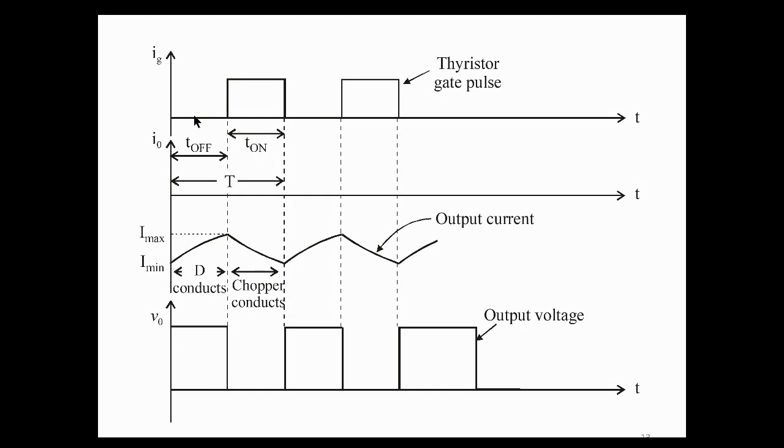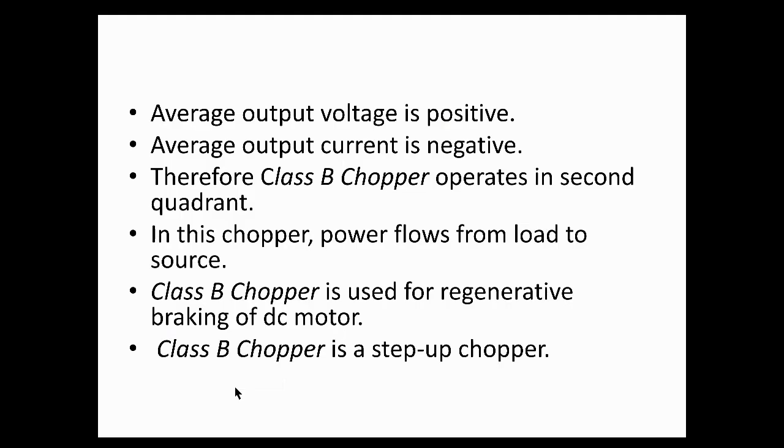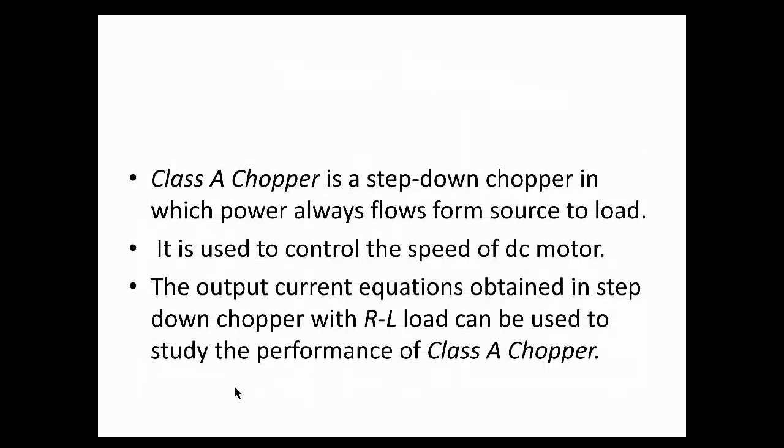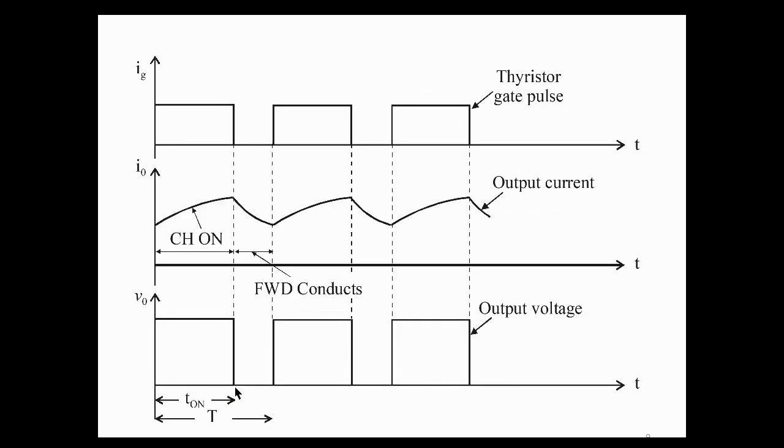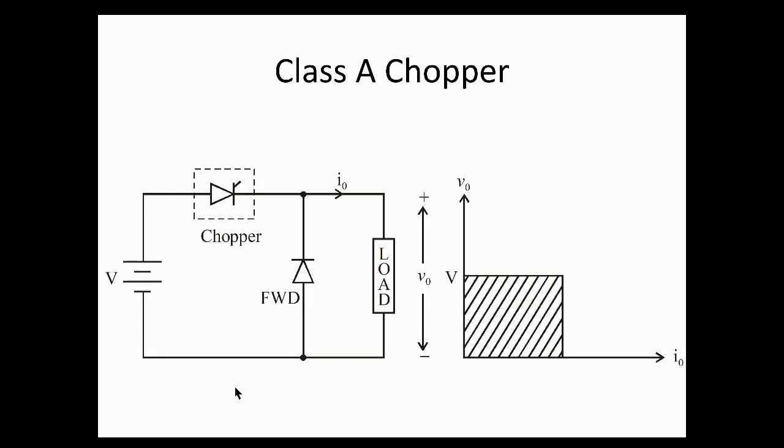When we don't have any pulse, what's the output voltage? When there's no pulse applied, we realize that we have an output voltage. When we apply the pulse and the SCR turns on, you realize that our output voltage is 0. If you look at the diagram, you'd have picked that up.